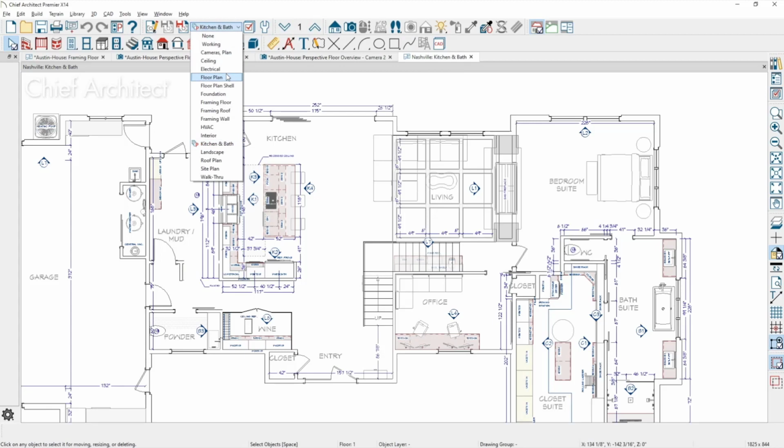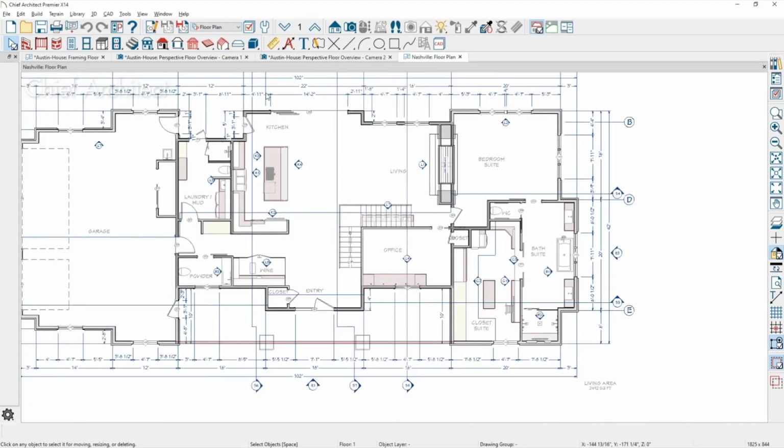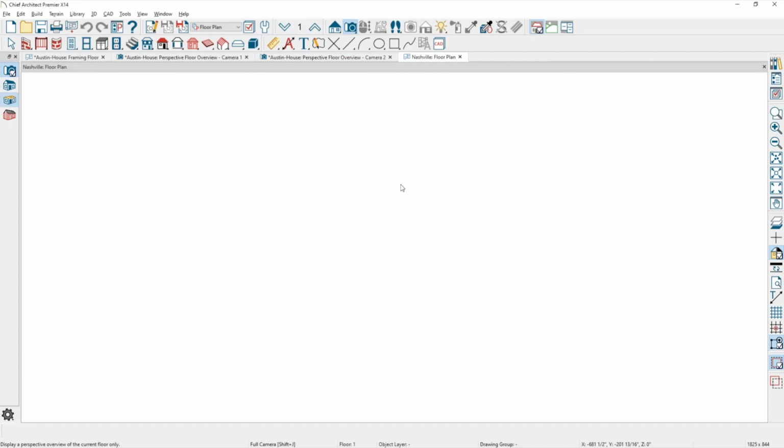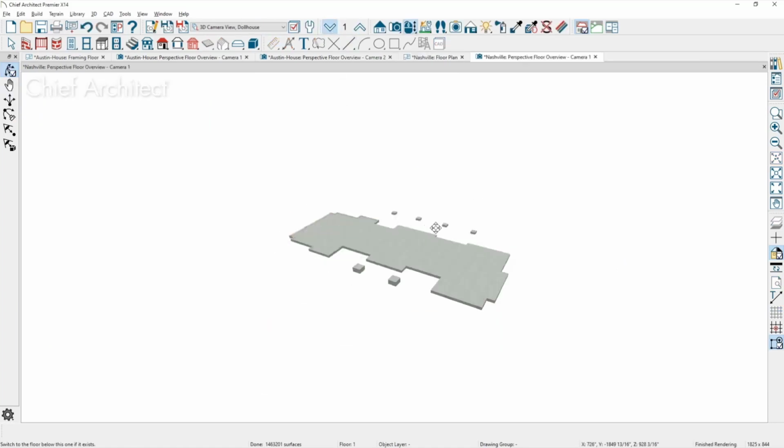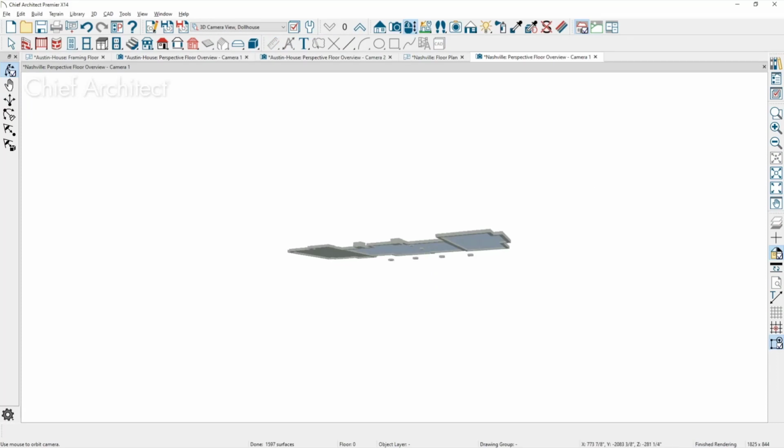Okay, so let's take a peek. I have something, I think, similar to that. Let me see if I have an example of that so we can see what we've got going on here. I think you could probably build a real quick 20 by 20 room, put a raised floor on top of it, and then manually build your mono slab next to it. It's really basic, I think. I thought I had an example here. Let me just grab one real quick. There we go.